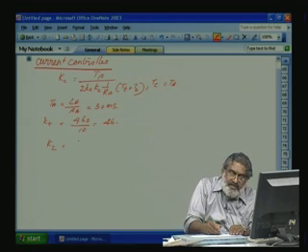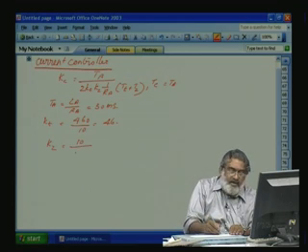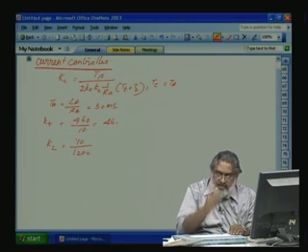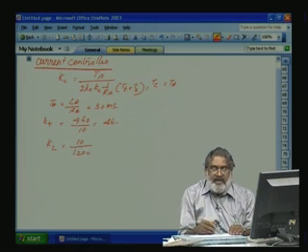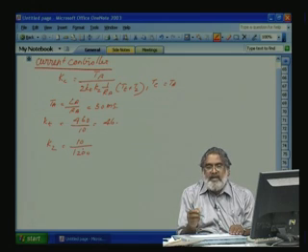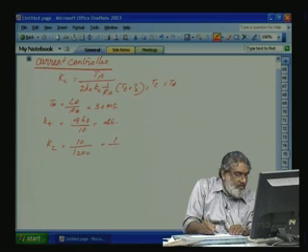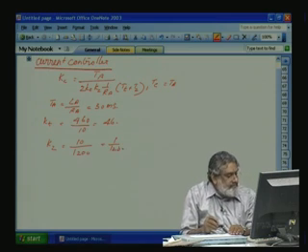So, K2 gain is equal to 10 by 1200. Here 10 is in the numerator because the controller output is 10 and the filter input is 1200, so we have to reduce the gain like this. So, the gain K2 is 1 by 120.